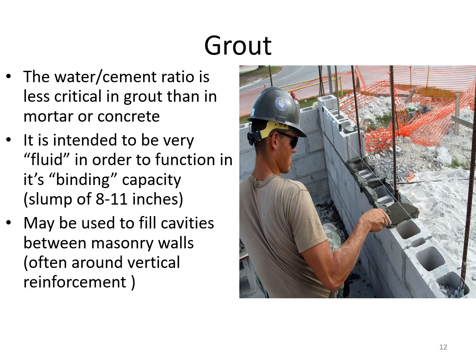And here, that's why at the bottom, you may be used to filling cavities. Well, now and then, there are certain areas that you do have to fill between the brick and the wall. Sometimes I call it a pancake of mortar or grout placed between the bricks just to give a little bit of adhesion. But it depends on the situation. Around windows and lintels, you may want to fill the cavity solidly. So the weep area is treated a little bit differently. You don't need a weep area when you need a little bit of cohesion between the wall and the brick facing.